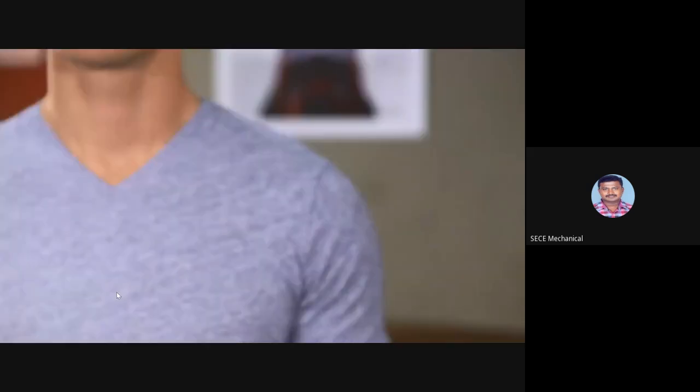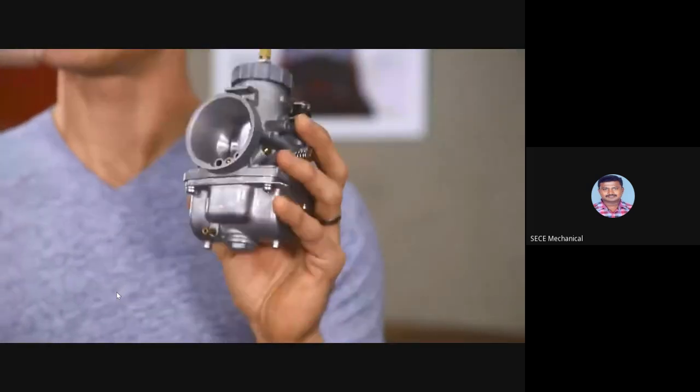Carburetors and fuel injection both have the same job to do, which is to mix fuel and air in the right ratio for proper combustion. Carburetors are your old school analog option, and they're what all motorcycles relied on up until fuel injection began to arrive in the 1980s. Nowadays, pretty much all bikes have fuel injection, though some scooters and small displacement bikes still use carburetors to keep costs down.